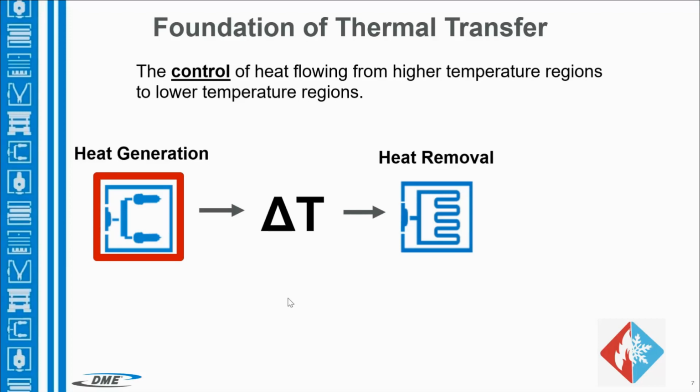And then you get into how clean is the surface of my tool. Because that cleanliness of your tool, that film that builds up as we mold, creates another path that heat has to travel through. And then you get into that process times. How fast can we cool the part to be able to eject it? So once we understand the heat generation piece, the heat removal, then we can start to really look at how we are going to optimize.